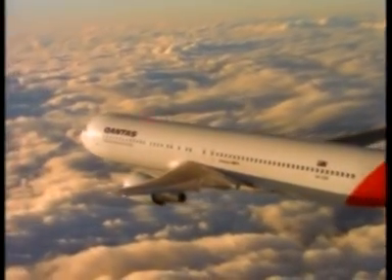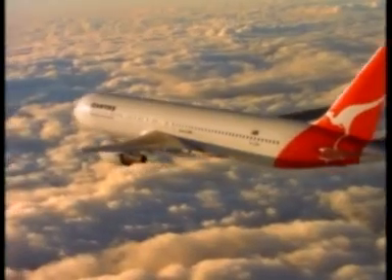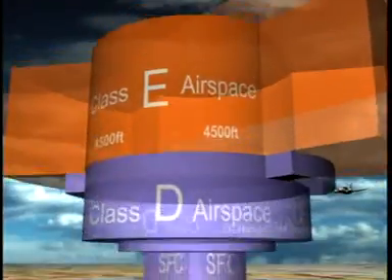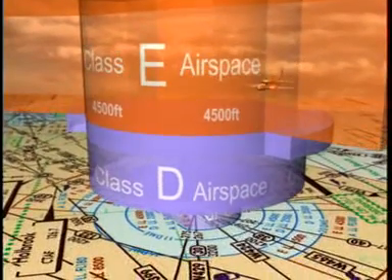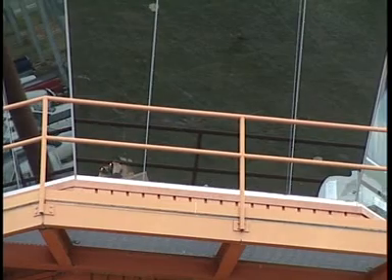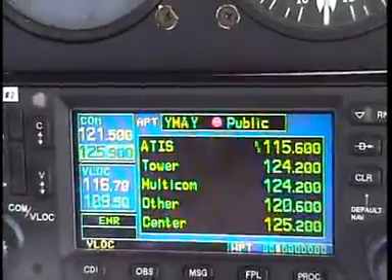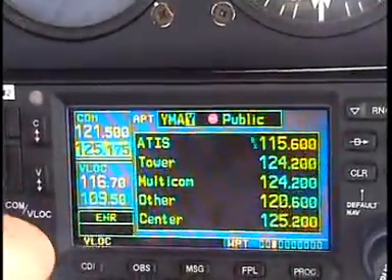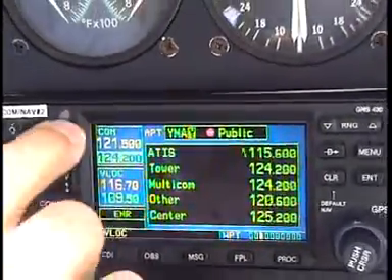Stay clear of the approach and departure routes of the aerodrome and also the instrument approach paths. Fly proper hemispherical levels, turn your lights on and keep a vigilant lookout. Maintain a listening watch on the Class D tower frequency as you overfly the airspace, as it will give you the best situational awareness of traffic in your area.